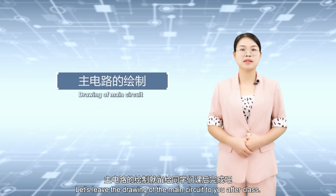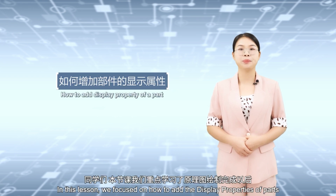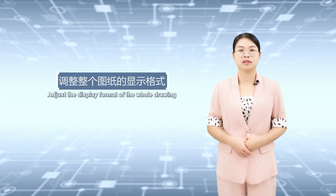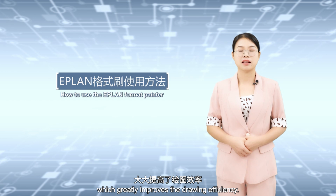Have you got it? Let's leave the drawing of the main circuit to you after class. In this lesson, we focused on how to add the display properties of parts and adjust the display format of the whole drawing after the schematic diagram is drawn. We also learned the use method of Format Painter in E-Plan, which greatly improves the drawing efficiency.